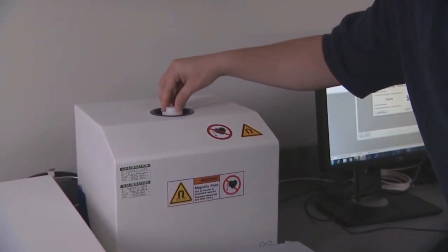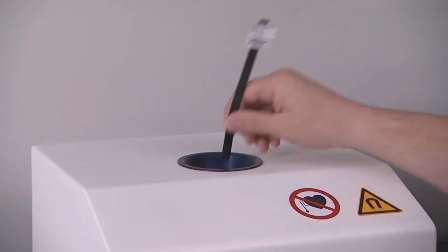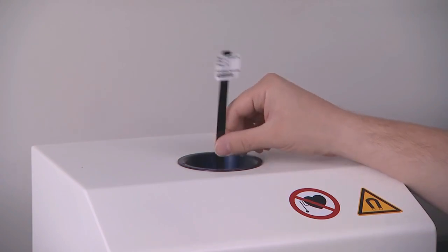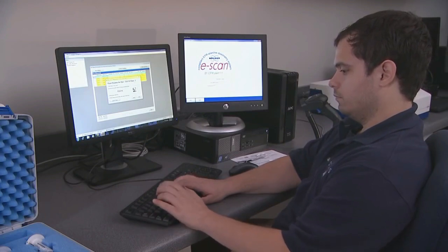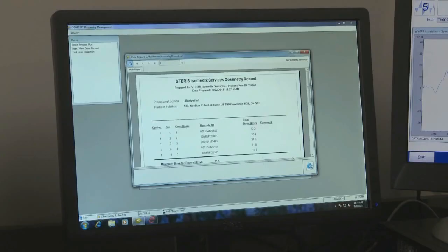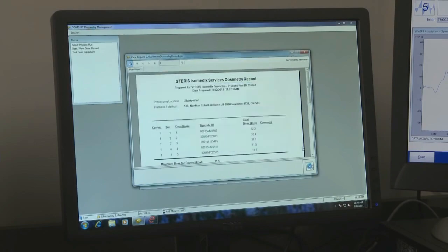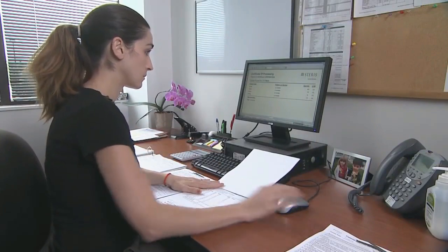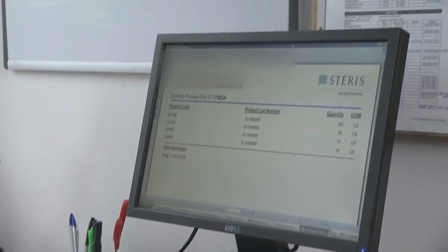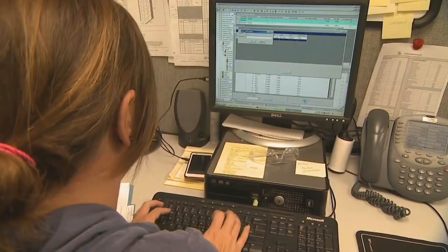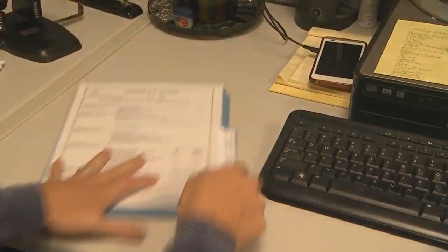The gamma irradiation process is not complete until the dosimeters are read and approved. Then, the dosimeters are placed into the dosimeter measurement device for measurement of response, which in turn is used to calculate the dose delivered to the product. Upon completion, a technician will e-sign the gamma dose record. Then, the gamma dose record report is electronically signed by a member of the planning team. Finally, once the quality team verifies that all the customer-specific processing parameters have been met, the product is now ready for shipment.